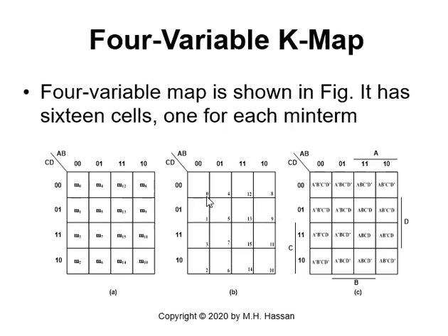We can fill out the value of the minterm at the corner. It's a good practice, so we don't forget the location of the minterm. 0 through 7, then we jump a column, then 8, 9, we jump a row, 10, 11, 12, 13, we jump a row, 14, 15. So this will be 15.